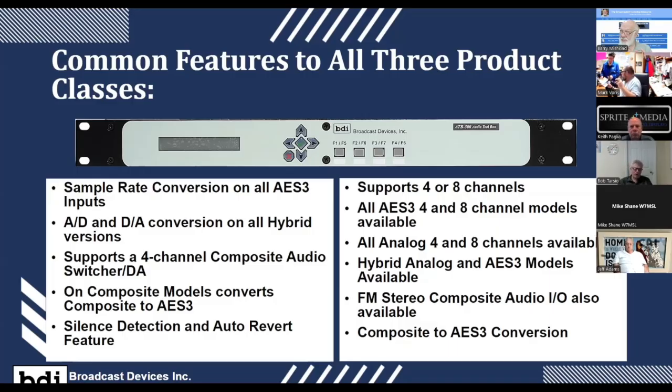We support 4-channel composite audio switching and DA as well. There's a module that you can configure these units with that allows you to do that. And you can also convert in the digital domain composite audio back to AES-3. It decodes left and right and converts it back to AES-3. And of course, all models have the silence detection and auto revert feature. Again, they support 4 and 8 channel features. All AES-3 models are available in the 4 and 8 channel models. You can do analog 4 or 8 channels as well.